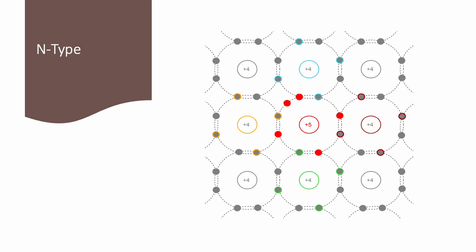Now to discuss further the n-type doping. Here we have the n-type silicon. It is created by introducing pentavalent dopant atoms, an impurity. Pentavalent means 5 valence electrons. So this is a pure silicon crystal lattice. The common dopants for n-type silicon are phosphorus, arsenic, and antimony.